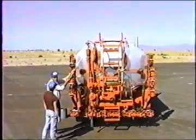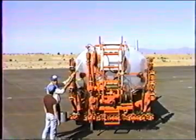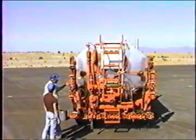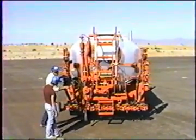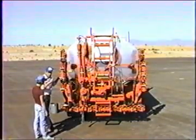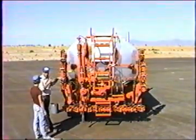When we turn that master switch on, that relief valve closes, so no longer can the asphalt go back to the tank. Also tied to the master switch is this main equalizer valve we talked about, the air cylinder on that. When we turn the master on, that main equalizer valve snaps open.